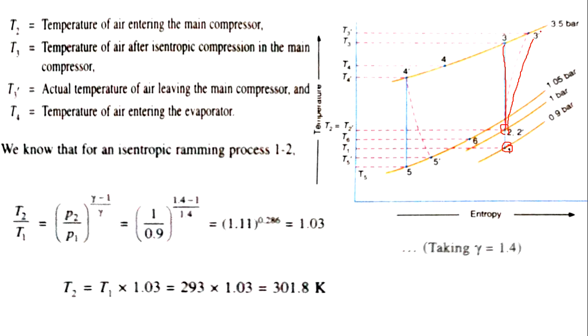The final pressure remains the same, and from there the compressed air is taken into the heat exchanger where it is being cooled, and the heat exchanger has an effectiveness, and then into the evaporator where the temperature is further reduced from 4 to 5, it is being expanded in the cooling turbine and the turbine efficiency is also given, so it is an irreversible process. It falls to 5 where irreversibilities are associated, and it goes into the cooling cabin.